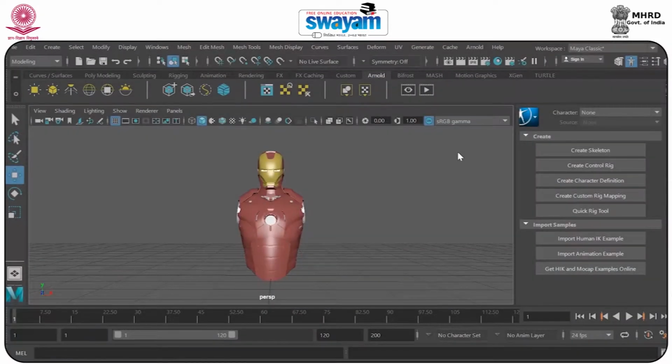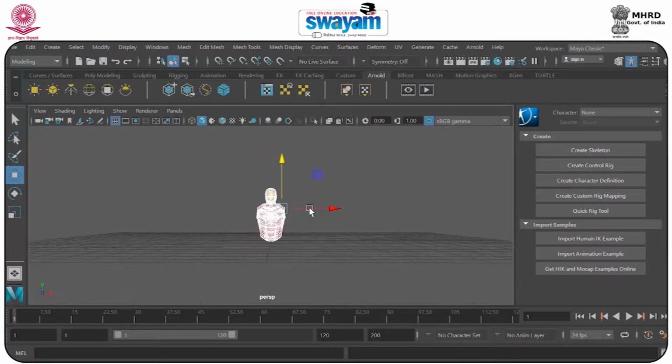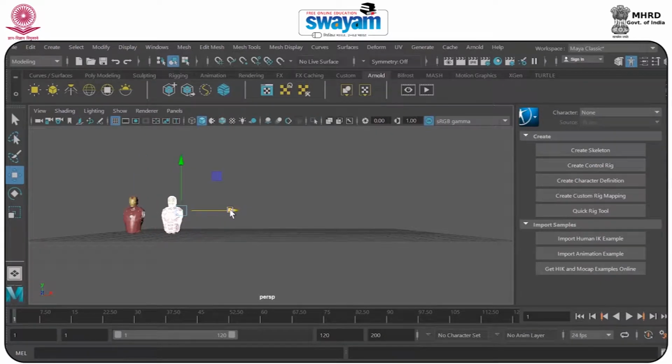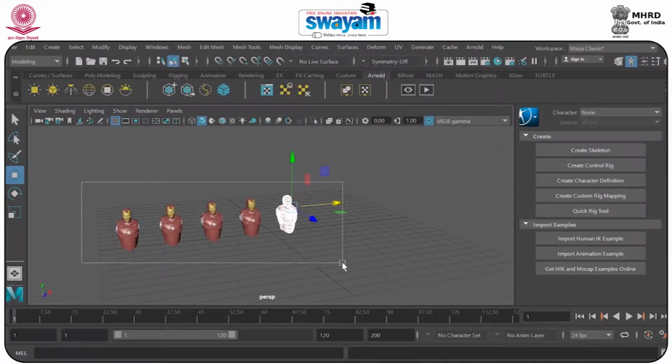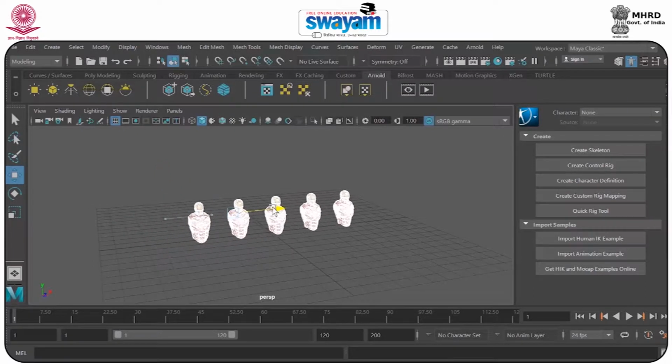Hi everybody, welcome to this course of Introduction to Texturing inside the Maya application. Right now I am using Maya 2018, and I have made this model, so I will start the concept of texturing with it. Let's get started. I will select the model and make some duplicates, Ctrl D for duplicate, and after that you can use Shift D for repeating the result. Okay, I have taken 5. I will select all of them and move them to the center.